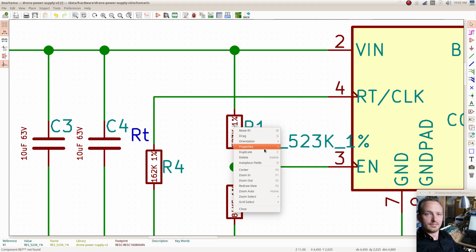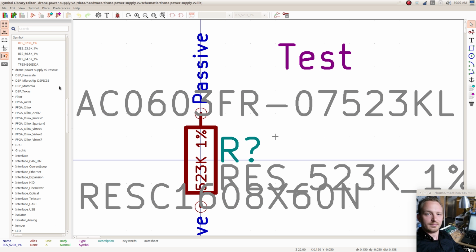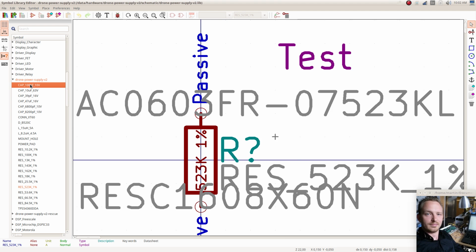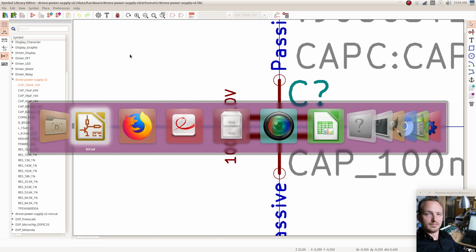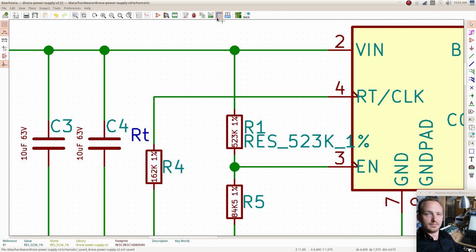So what we usually do is go into the library. I would open the library editor, go into my local project library, click on every single symbol, and from here I would set the footprint. It should be correct once you create this library. You should have all the fields correct. But what I really mean is that it would be really nice if in this other dialog here I would be able to back import the fields into the library. But I shouldn't be using this dialog right now for assigning footprints, because that functionality is simply not there.